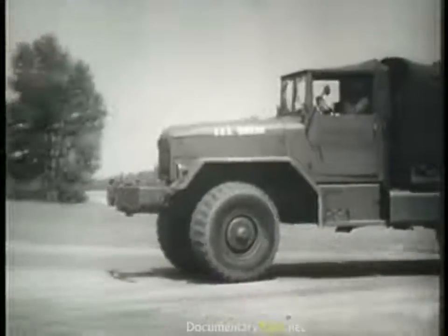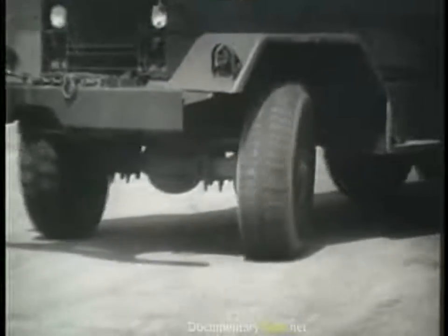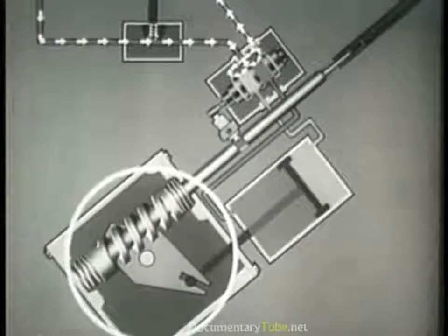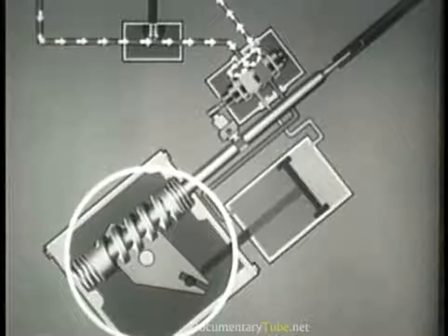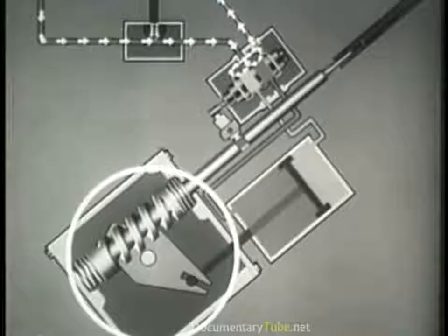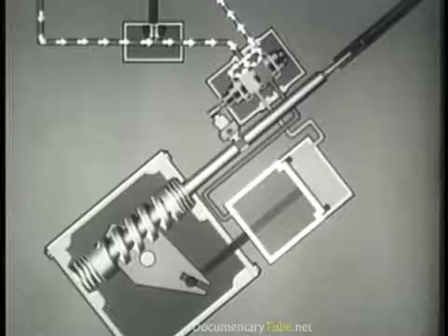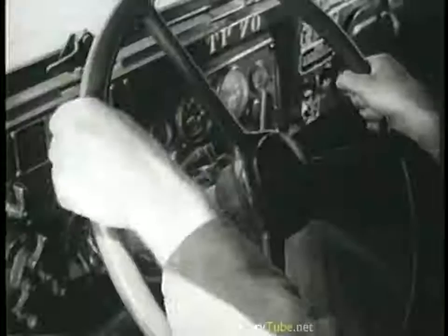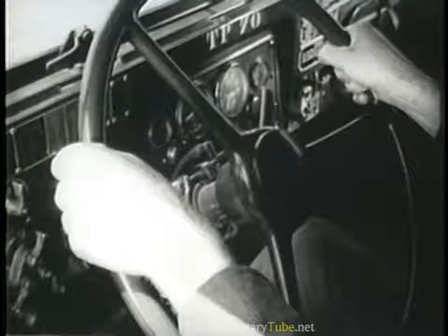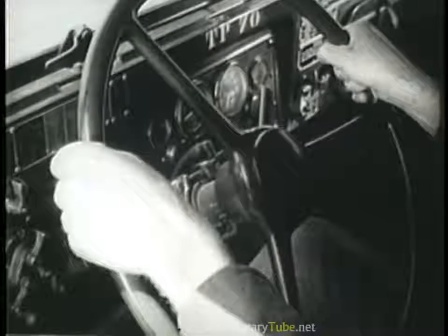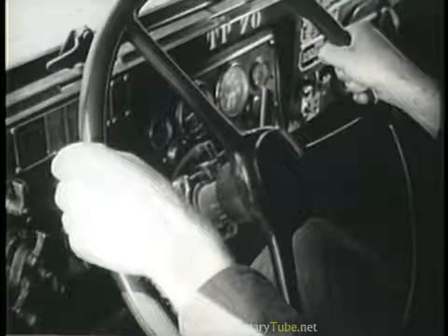When the front wheels are held in a constant turn, the cam will not be rotated. The pitman arm shaft lever is held stationary toward one end of the steering cam by the increased pressure on one side of the piston. The tendency of the steering geometry to return the wheels to the straight-ahead position is overcome by the driver, who maintains a constant force on the steering wheel in the direction of the turn.